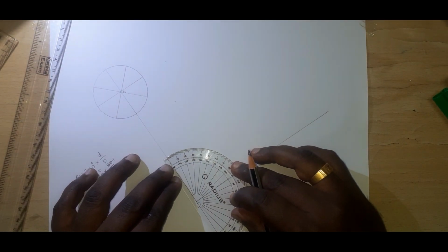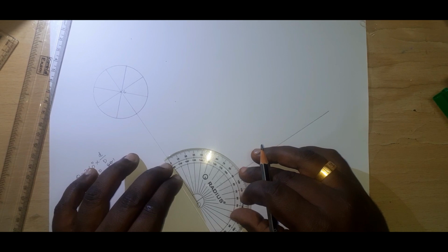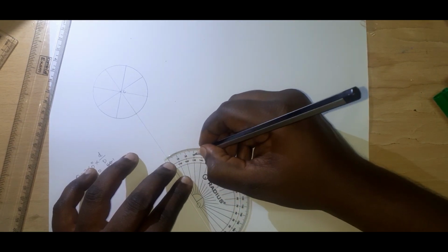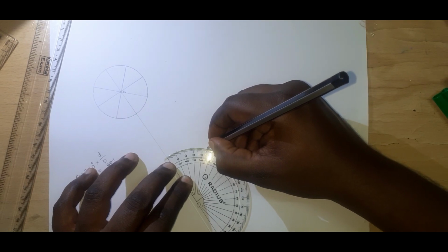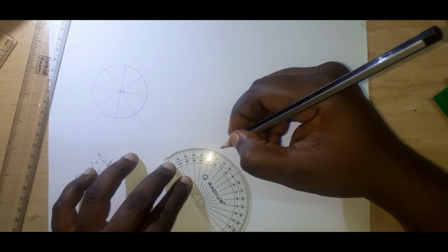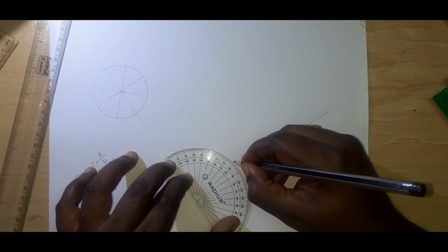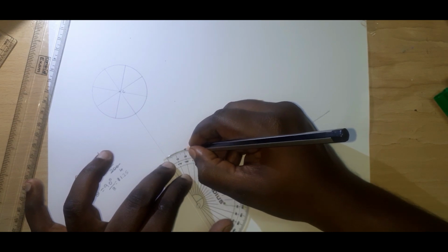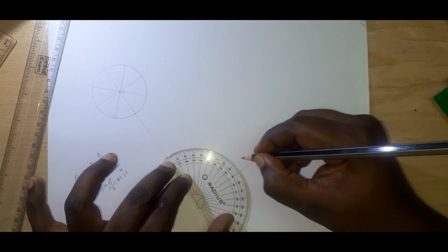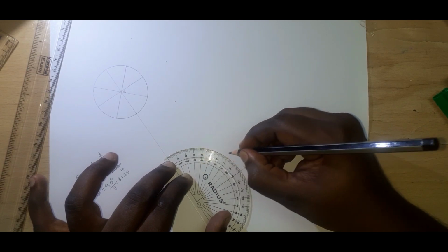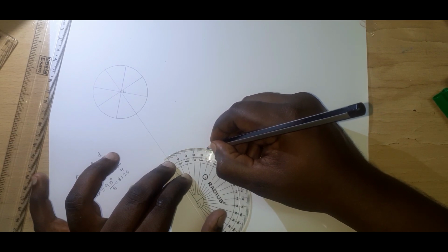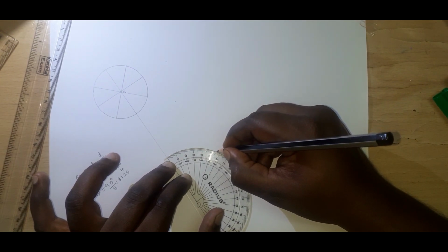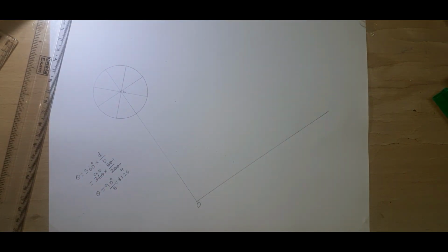So here we need to mark the difference for that, 11.25, approximately. I can make it here, and 90 has to be divided into 4 equal parts, which will be 22.5, 45, 67.5, and the remaining half we have to make it. So that is 11.25 each. So we have made 8 equal parts.